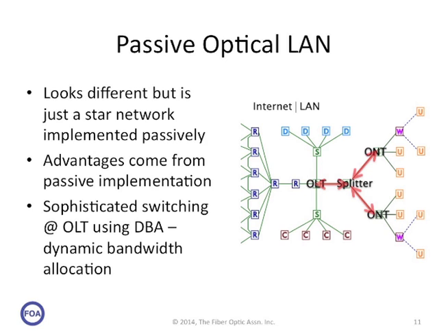The OLT uses time division multiplexing to steer data to the appropriate ONT or user and to handle upstream combination of signals from the various users. It uses some very sophisticated switching, which was necessary because these systems often had large numbers of users, thousands or tens of thousands in fiber to the home. So it does what's called dynamic bandwidth allocation, to dynamically allocate bandwidth where it's needed and create an extremely efficient network.